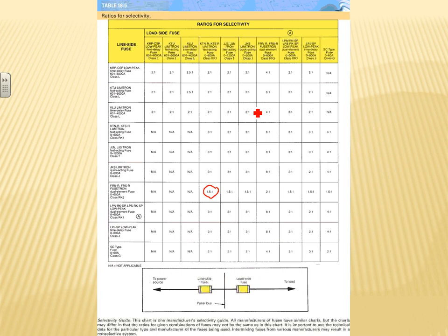Four to one. Yeah, 4 to 1. You go higher than that. I mean, most of the panels I use are 225 amp panels, and a lighting and receptacle panel, 225 amp, you barely can use it. Most of it is 20 amp anyway, right? 20 amp, maybe 30 amp for some equipment, a typical lighting and receptacle panel.